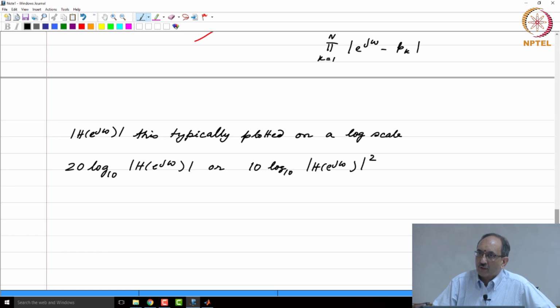These are 3 orders of magnitude apart, and you will not be able to see this 10 to the minus 3 versus 10 to the minus 6. You will not be able to see the difference if you plot this on a linear scale. Difference in the stop band of 2 filters that have rejections of 30 and 60, no way will you be able to see this on a linear scale. To see the difference, you need to see this plotted on a log scale for you to make out the difference.